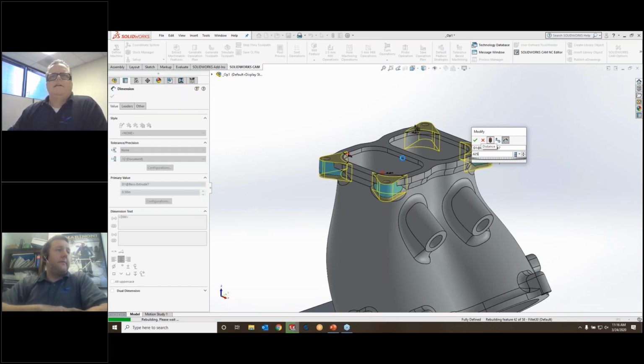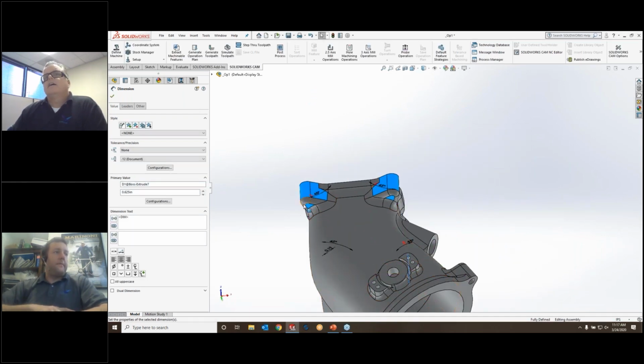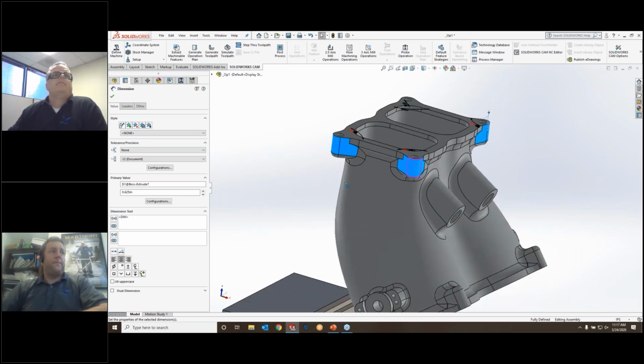So right in here, right? The intake ports, is that where you want me to do it? Yeah, right in those ports, yeah. Just put in a 3-axis rougher and finisher just to clean up that first section of the ports, and I'll do the rest on the 5-axis. Okay. I can make that happen. So I'm guessing that's good now, right? Closed holes is what they want? Yeah, that's it, yeah. Okay.